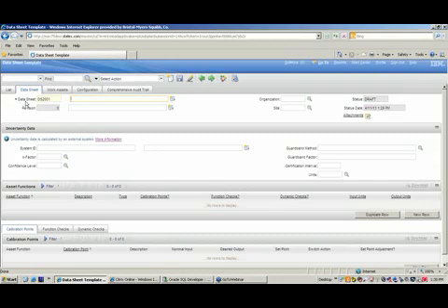You may have multiple assets that actually fit under the one category. So any type of data sheet can be used for multiple assets itself. So you're not really defining a particular asset, you're defining a process here to be calibrated. So again, if this is to be done as a scale, you identify it as a scale, you identify the range, and we'll put it at kilograms, and basically we'll look at the same on the other side as well, input and output. So again, we define the process that the data sheet is going to be using here.